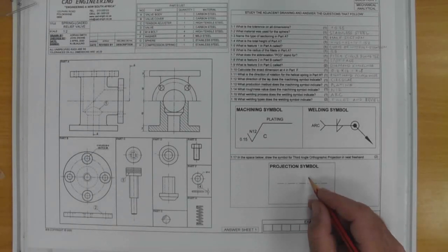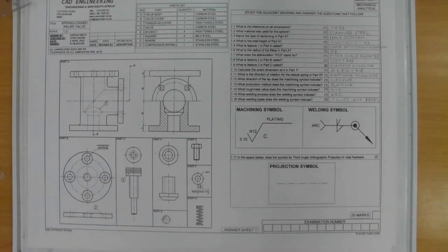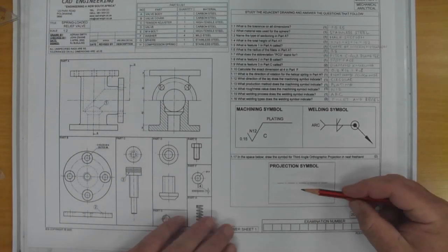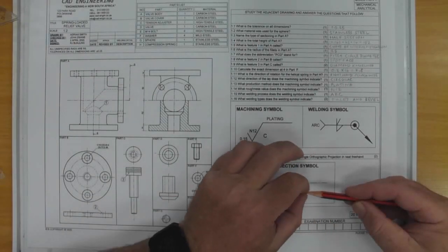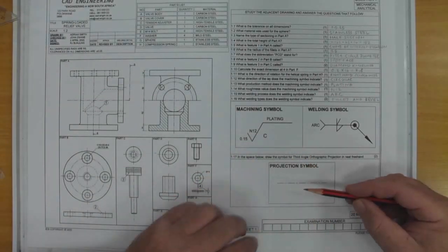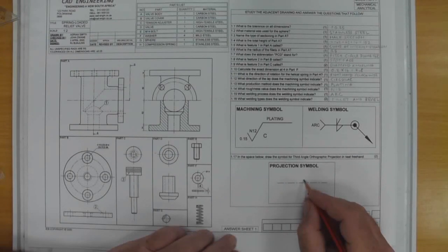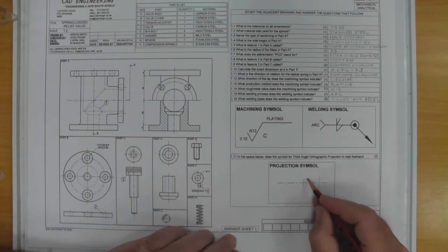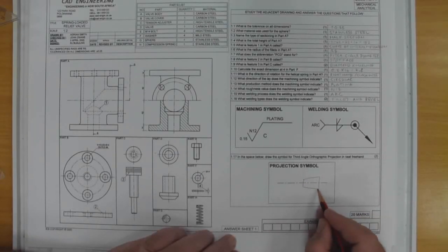Okay, the projection symbol. The projection symbol is for third angle. We're using third angle, and the projection symbol is always the tapered roller and the circles. Now the tapered roller is like the end of my pencil if I had to cut it off, so it's tapering, it's narrow at the tip and gets bigger. So we've got to do the same thing here. It's narrow, so I'm going to draw a narrow line on this side, leave a bit of a space, draw a longer line on the other side, join up the edge and join up the edge.